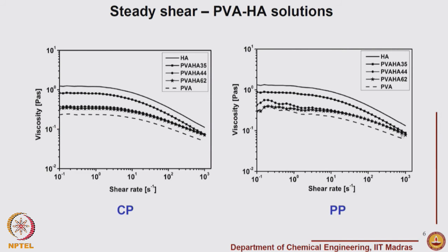Right now, at least immediately highlighting, I can't see any other difference. I can see also, for example, the circles and the stars are much more different, but everything is related to these low strain rates. From 0.1 to 1, basically the low viscosity materials in parallel plate seem to have some fluctuations in data. Now again, you will not find any information in any of the resources to say whether this is a real material response, or an artifact, or something where the assumptions I made during rheological analysis are not valid.